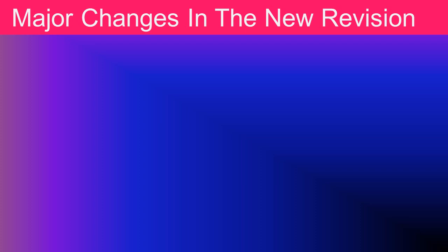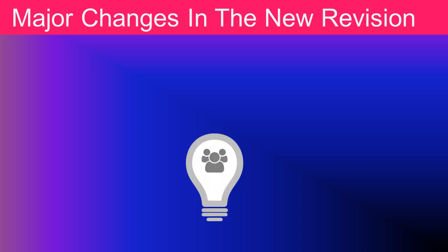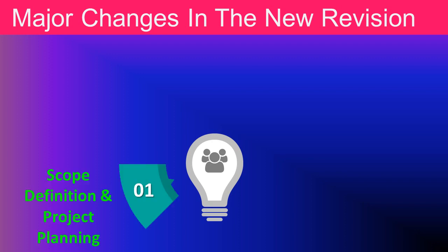As per the new guideline, the FMEA is carried out in 7 steps. These 7 steps provide a systematic approach to perform FMEA and serve as a record of the technical risk analysis. The first step is scope definition and project planning. Its purpose is to describe what product or process is to be included and excluded for a review. This allows you to review all processes at a high level and determine which processes will be analyzed.